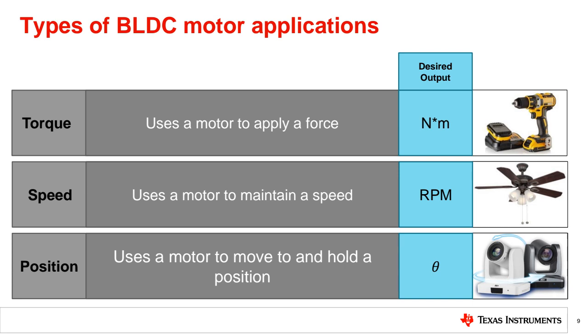They have different requirements and different challenges. Torque applications demand zero or slow speed torque. An example of this is a drill that is screwing in a screw, and the screw hits something where the torque needed to drive in the screw is larger than the drill can deliver. So the motor will spin down to zero or slow speed, but the drill will still need to deliver torque to screw.